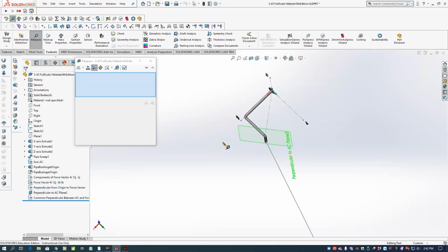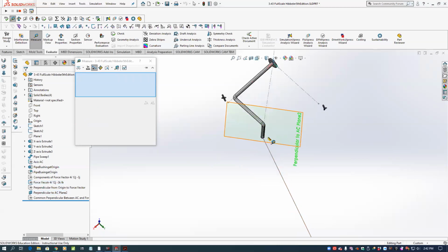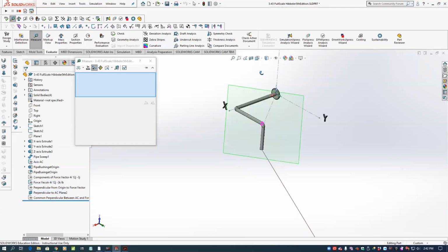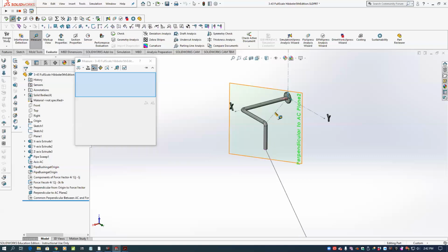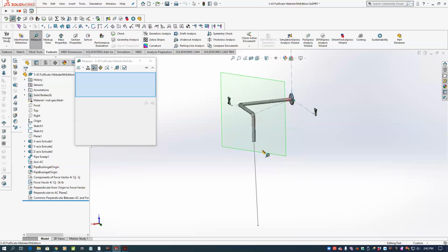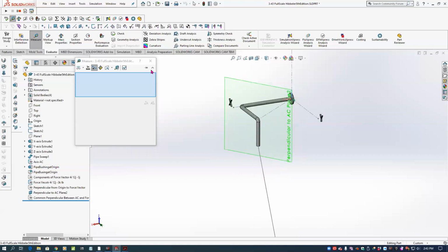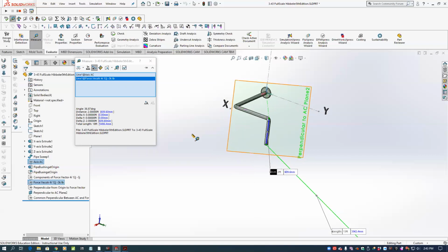So the cosine of that angle, 53.13, times 13 would be the force that's creating a moment, and then the perpendicular distance from that line to this line. In other words, those are skew lines. They are non-intersecting, non-parallel lines. And if we see what the perpendicular distance is from there to there, that just gives us a straight line distance.